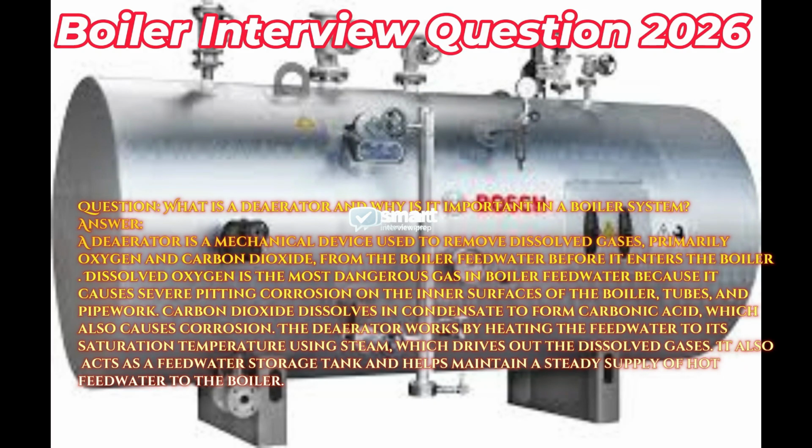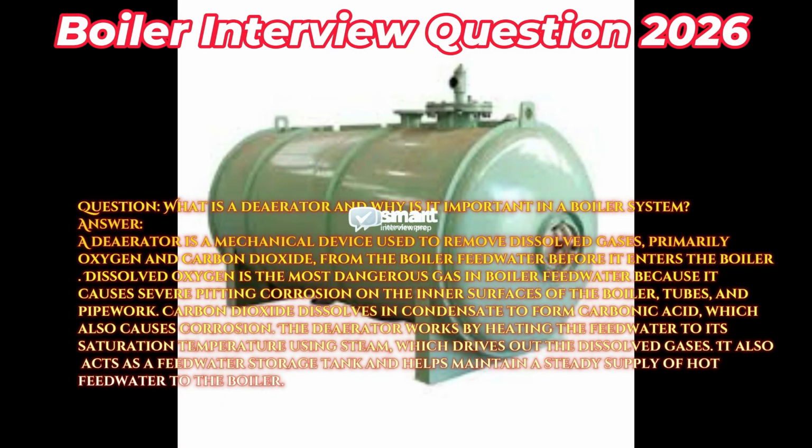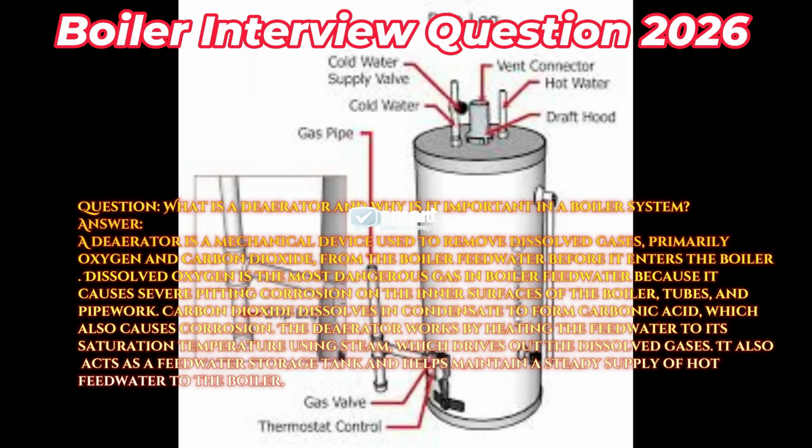The deaerator works by heating the feed water to its saturation temperature using steam, which drives out the dissolved gases. It also acts as a feed water storage tank and helps maintain a steady supply of hot feed water to the boiler.